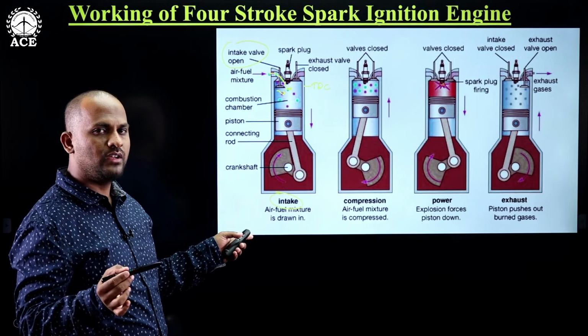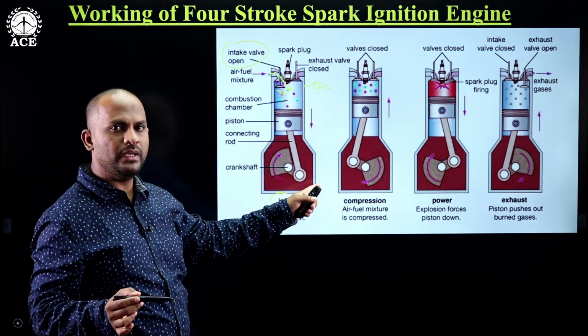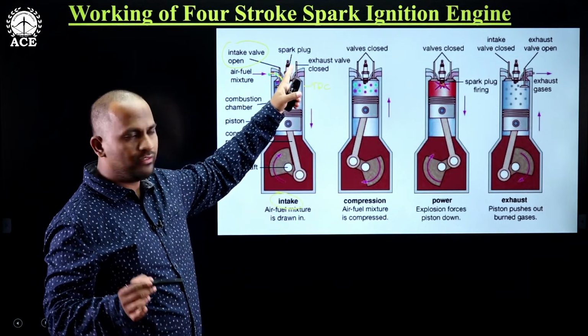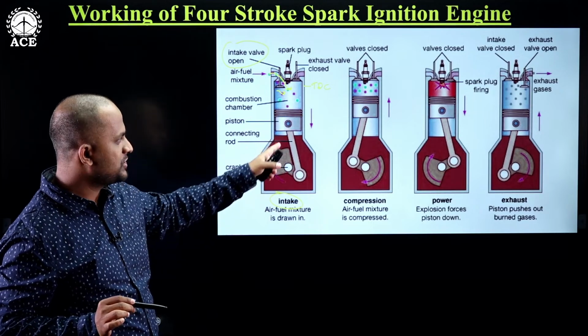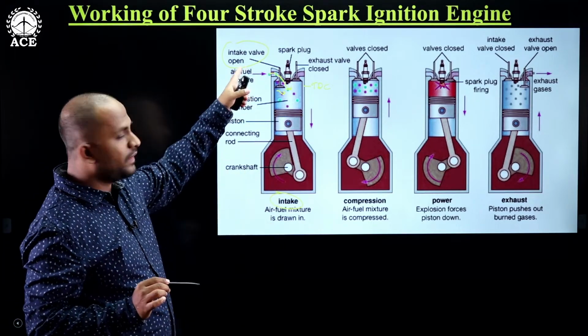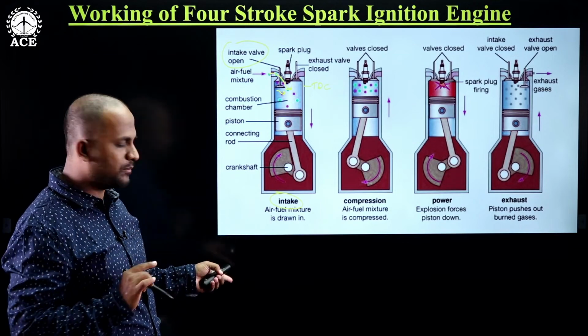At that time, in which direction is the piston traveling? It is traveling from TDC to BDC. And what about the exhaust valve? It is closed. Now, when the piston reaches the BDC point, the intake valve will be closed. Now it completes the suction or intake process.